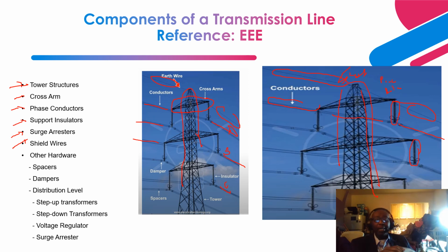The typical impedance for the grounding points of these transmission line towers is about 25 ohms. At distribution voltage level, you're supposed to have about 15 ohms of ground resistance, and for higher voltages, it's about 25 ohms.